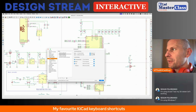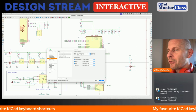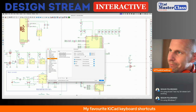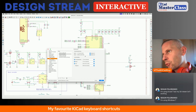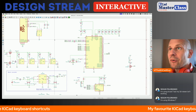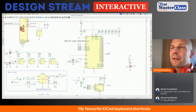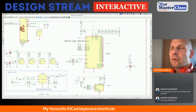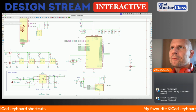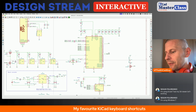Grids, yeah, here is option 1 on my Mac, and option 2 grids. 50 mil grids is the standard, option 1. 52 is for labels that should be placed on a more fine grid. Since I think KiCad 8, or 9, I don't know, there is grid overrides. So it works like when you are placing,